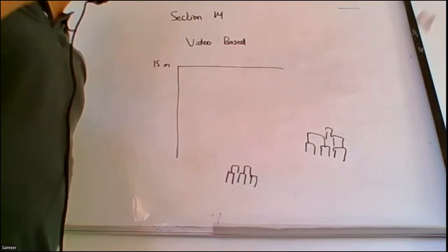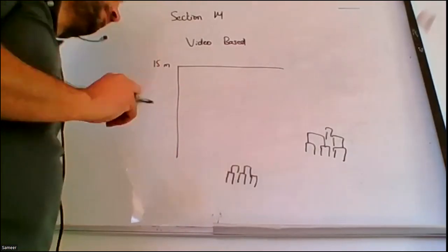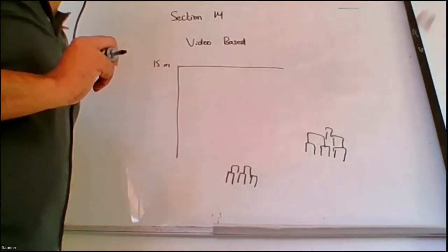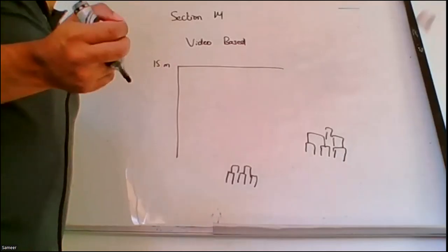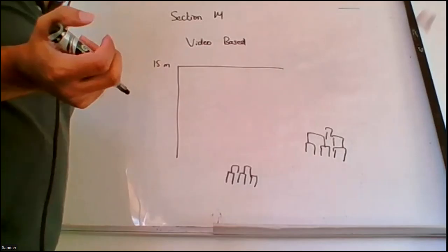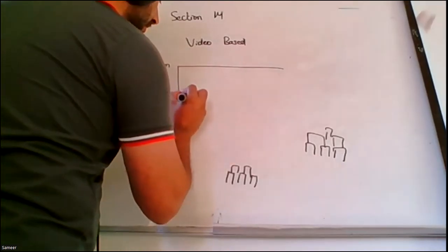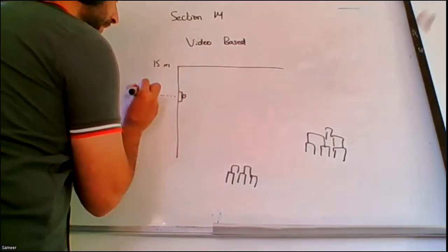I know that the material, at the initial stage, is going to give me smoke. Let's say it's a wood material, a class A combustible; it's going to give me smoke at a very initial stage. So I want to have a smoke detector, but the ceiling height is very high, so here the only option that I have is a beam detector. Now the beam detector that I'm going to install here, the requirement is 10 meters and above, right?